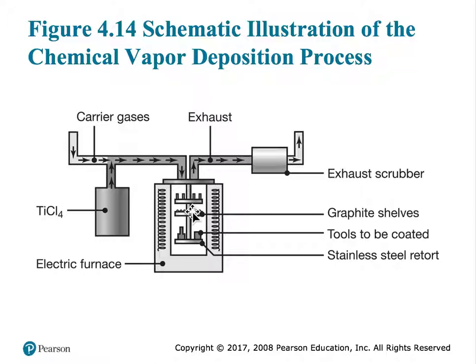So that final surface, when it is being used to machine and things like that, will provide very low amounts of friction. So it can easily move on top of the other surfaces and machine them. And the other advantage is that the silicon carbide or the titanium carbide would be extremely hard and abrasive with respect to the substrate material.